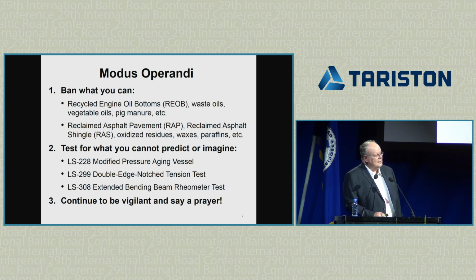So lots of other things that are less outrageous, but that are widely used are waxes as warm mix additives. Sounds good, doesn't it? Warm asphalt, environmentally friendly. In Ontario, we just lost a contract. It was 80,000 tons of hot mix on a freeway, 300,000 cars a day. It had warm mix additive in it. Only 1%, that's not a lot, it doesn't matter. Well, it does. 1% of wax is very bad for your low temperature cracking.